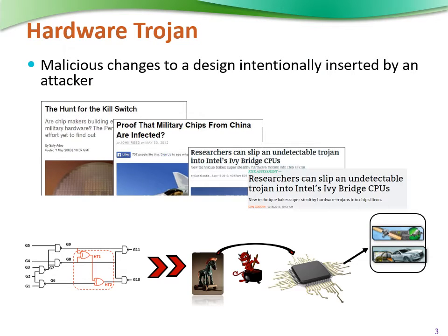Hardware Trojan is one of the most severe issues that we can see recently. It is a circuit that can be inserted by a third party to take control of the whole system at some point when the system is in use. It is a circuitry that will trigger when a special scenario appears, maybe even based on timing.